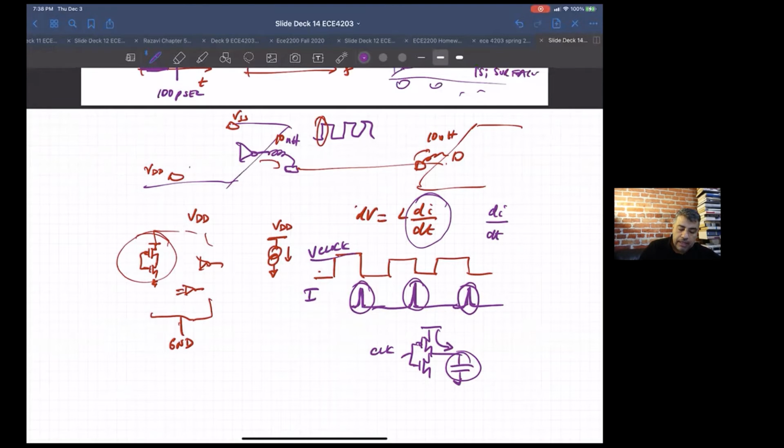So what happens here if I have an inductor? Let's say this is the silicon side, this is the package side. I'll have VDD here, and every time I get a pulse, I'll get VDD minus this delta V, which could end up being a big number, hundreds of millivolts if you're not careful. And as soon as it gets bigger than the noise margin of your logic, or God forbid, the noise margin of your flip-flop, you're basically in deep trouble.